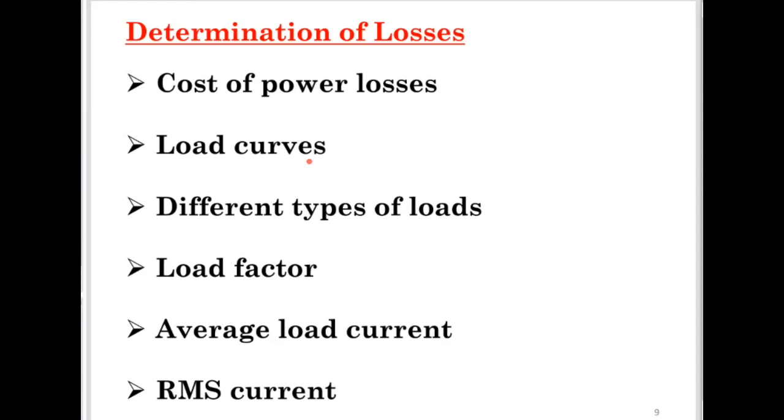So average load can be calculated for any type of load curve, irrespective of its type, for example a daily, monthly or annual load curve. That's why we need to look at the load curve. And the maximum demand, meaning the maximum load, we can easily find out from the curve.